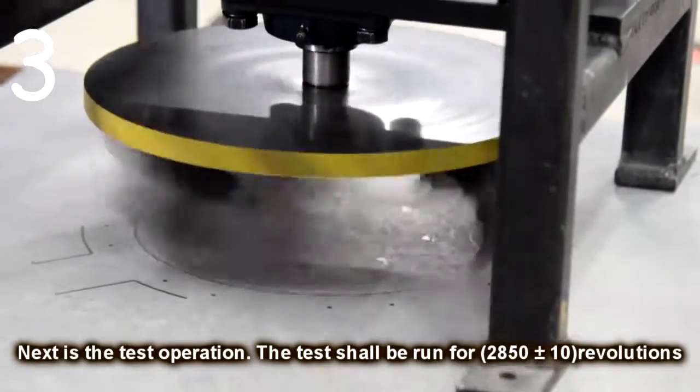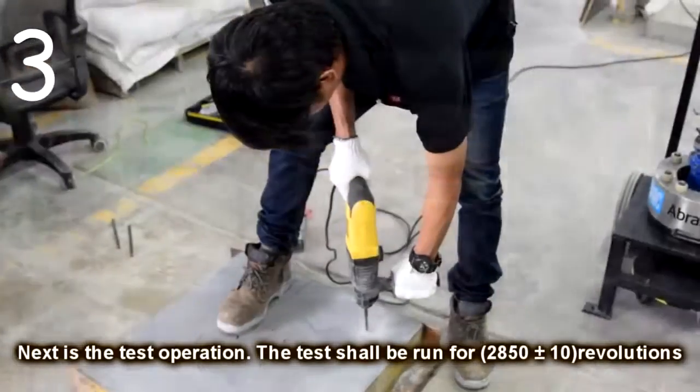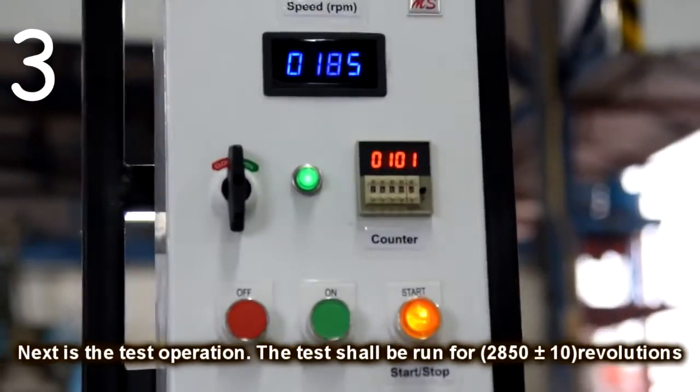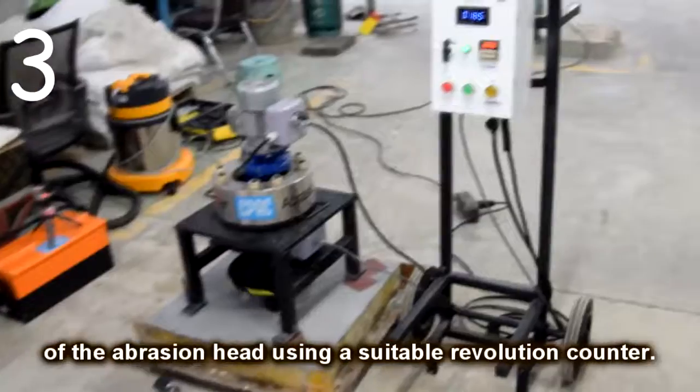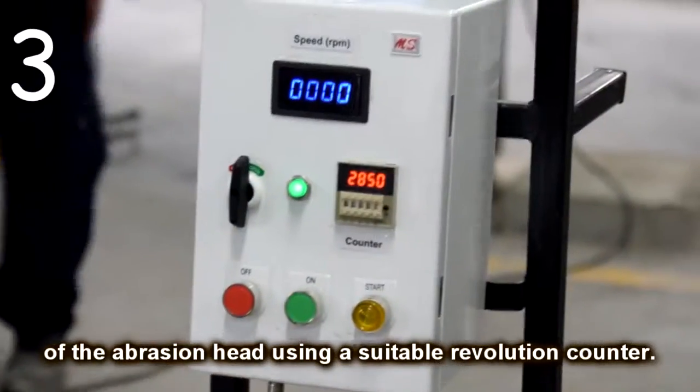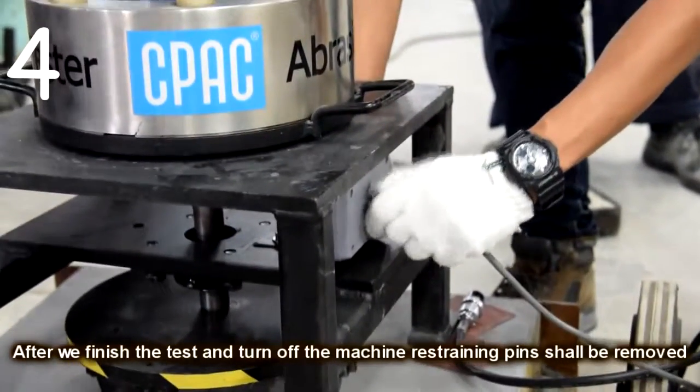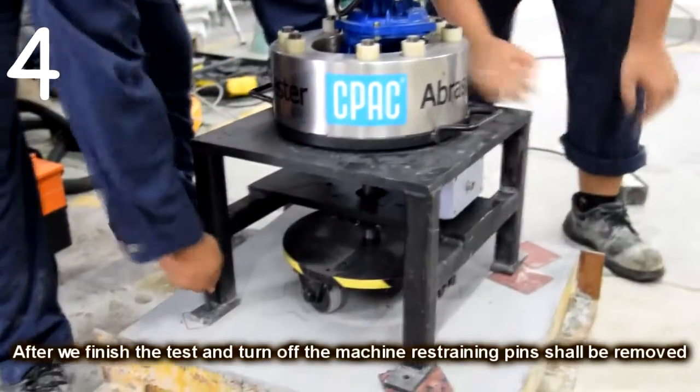Next is the test operation. The test shall be run for the 2850 plus or minus 10 revolutions of the abrasion head using a suitable revolution counter. After we finish the test, then turn off the machine.